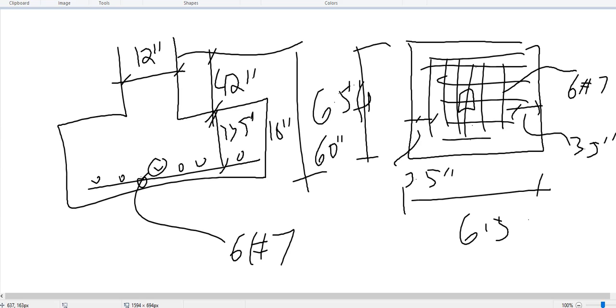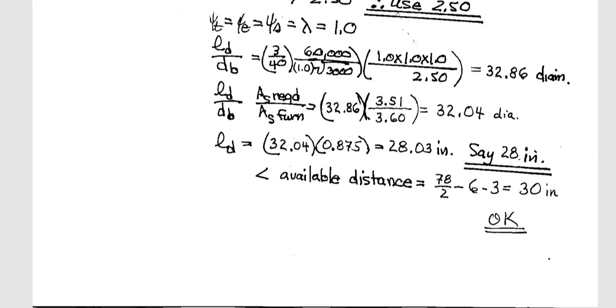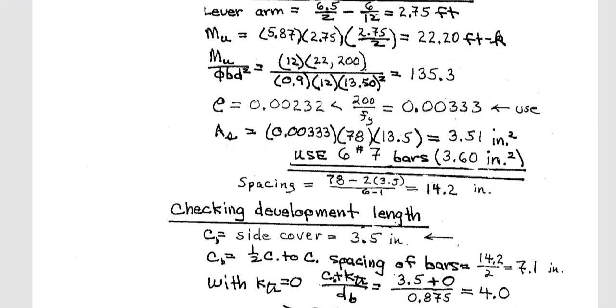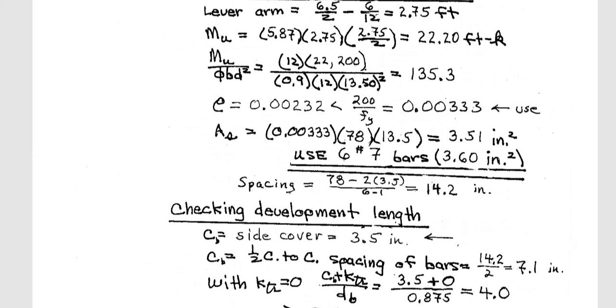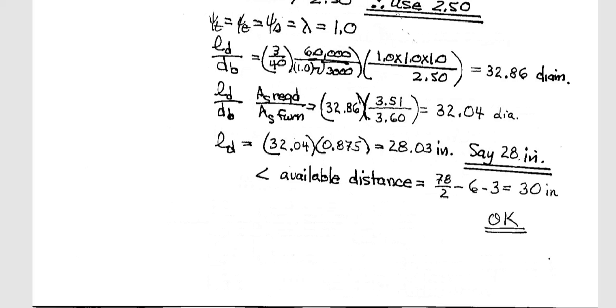So hopefully you understood what square footing design is. There's something different from the column. In column, we do not need punching shear, but in square footing, we need this punching shear. Now, what about rectangular footing? Exactly the same thing. We need the punching shear for rectangular footing. The only difference will be the reinforcement arrangement. So I'm not going there.